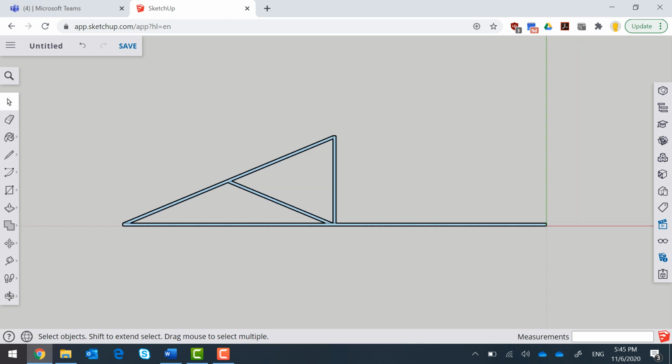Very good. Now, what I would advise you is, if you have a symmetrical bridge, is to finish one side to make sure that it's 100% perfect. And what you can do is the following. We can select what we want to copy and to be repeated on the right side. We can go to Move, and on your keyboard, press Ctrl and drag your pieces to the endpoint here.